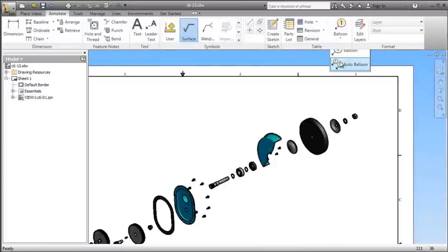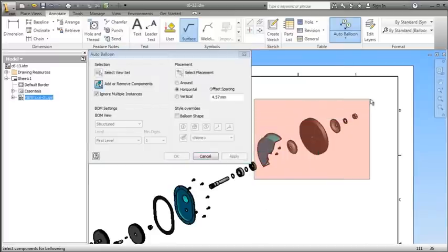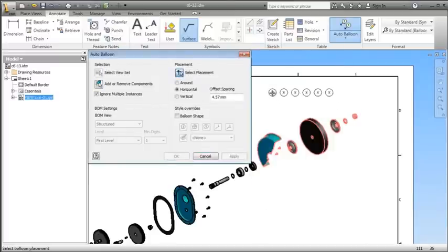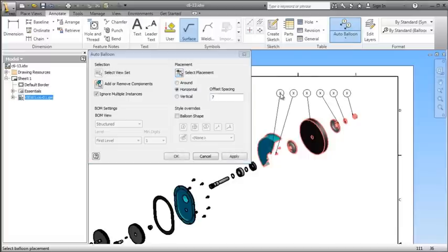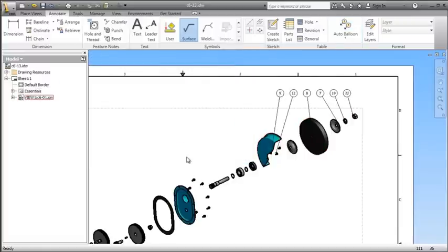Here in this assembly drawing, we can go ahead and add balloons individually, or we can auto balloon a group. We can tell it to show us a preview of the horizontal placement, the vertical placement, placing it all around the place. So here we were able to just go back to our horizontal. If we want, we can even change the spacing in between the balloons to spread things out a little more and go ahead and drop that in.